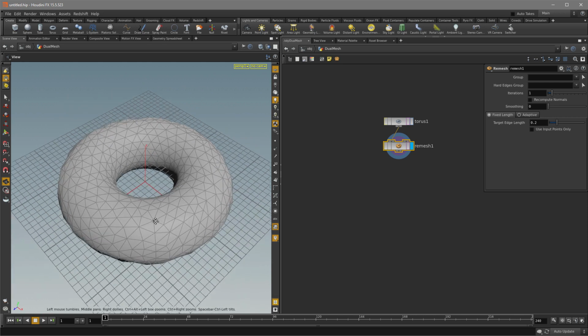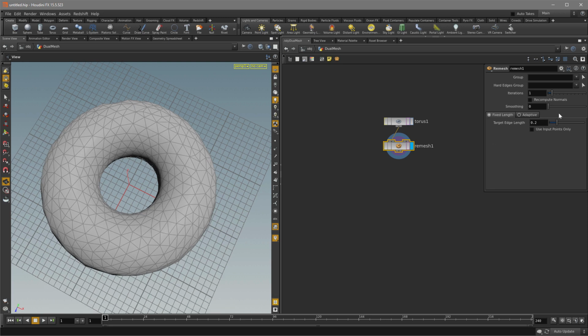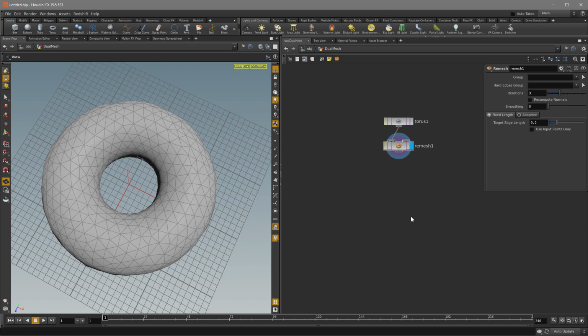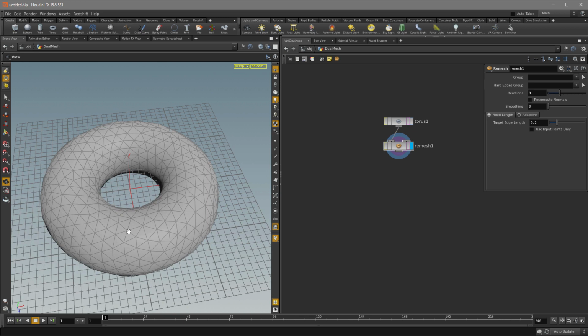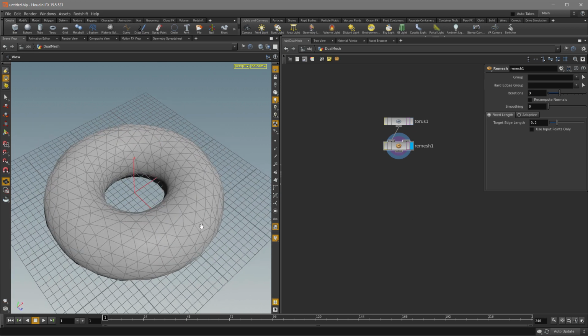That is looking quite good. To improve the quality of the Delaunay triangulation, we can up the iterations, say to 3. And the area of the individual triangles will be a little bit more even. And then we would want to create the second mesh, which is the honeycomb structure. And we can do so by computing the dual graph to this Delaunay triangulation.